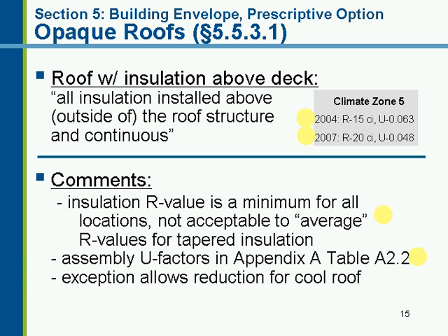Now this might seem curious, but you know that the sun is very high in the sky during the summertime, so the high R value of insulation in southern climates helps reduce the cooling loads in the summertime, whereas the high insulation R values in the northern climate is more used to keep the heat in during the winter heating season.